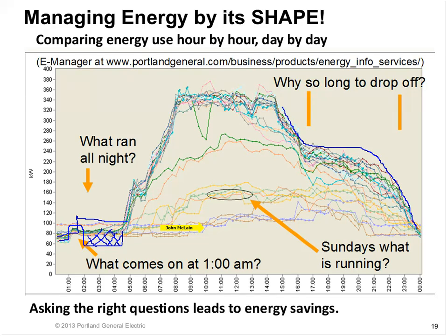You have lighting load. So they renegotiated with the janitorial service and said, I want you to turn all the lights off and only turn the lights on in the rooms you're cleaning. And so suddenly all this stuff started going away. And again, the shape looked a lot more sensible given that, gee, how many people were actually in the building. The load didn't represent that. So they saved all of that.